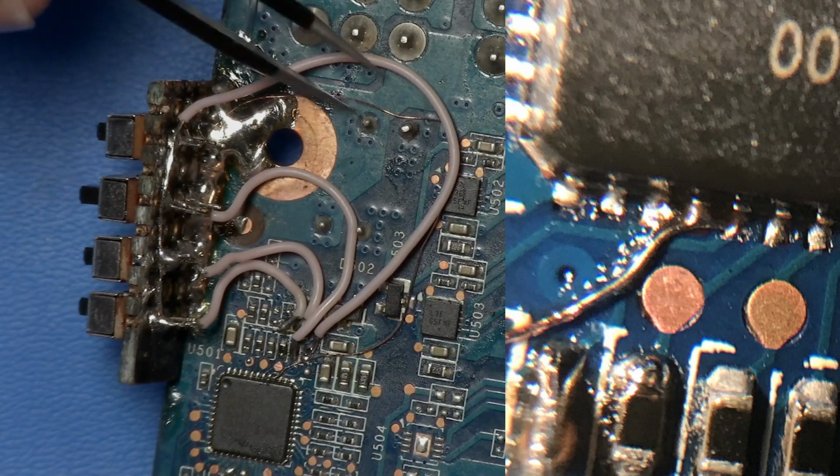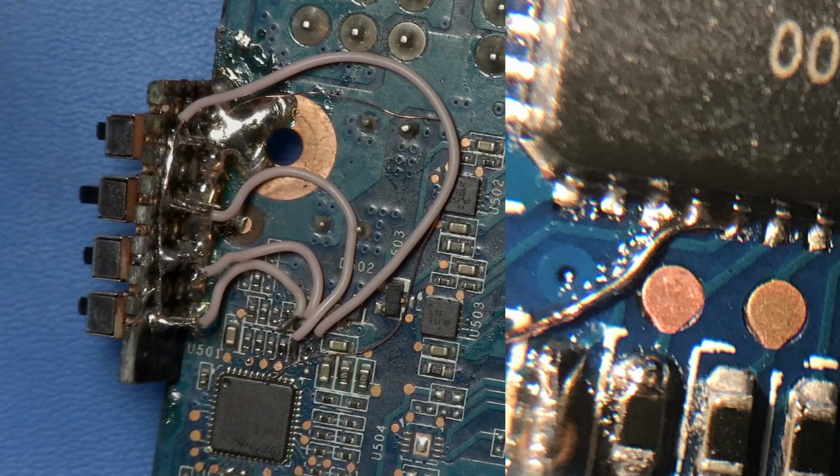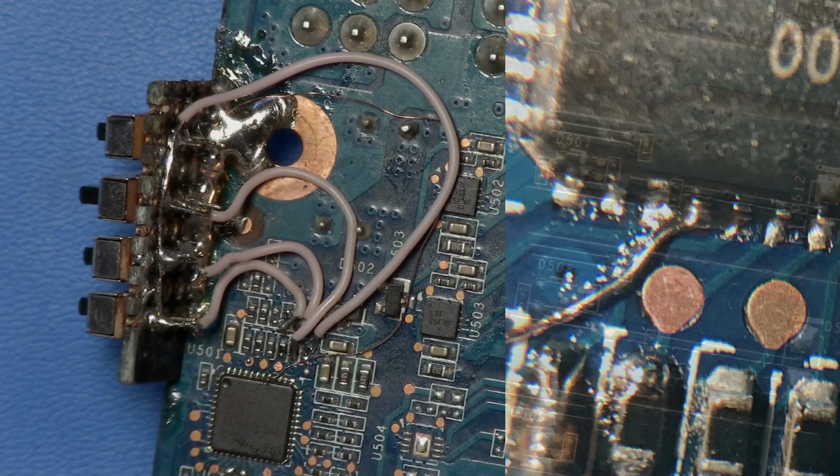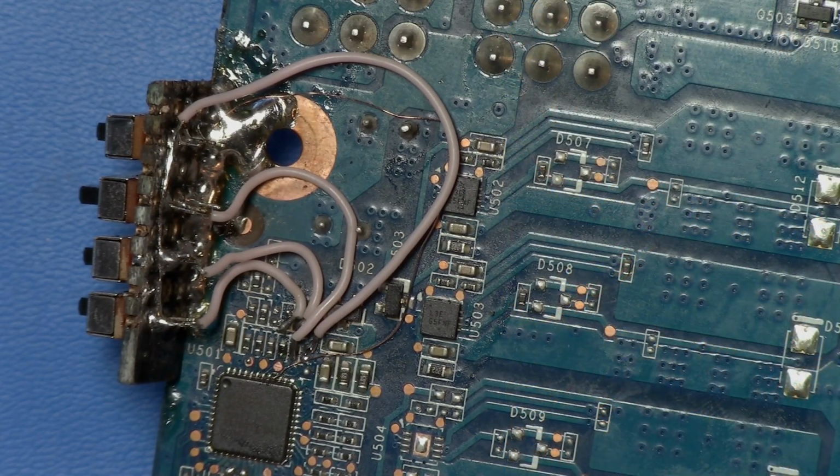Basically, to do that, I just used a ton of flux and make sure you don't have too much solder on your iron. Carefully hold the magnet wire right near there after it's been pre-tinted and just kind of jam it into the controller pins. And with enough attempts, I managed to do it even without a microscope, so I'd say it is very doable. You just need some magnification to be able to check later if it's soldered properly.